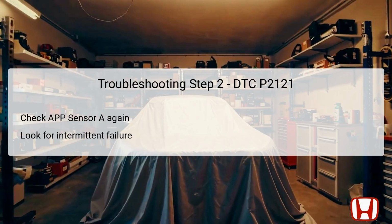If the readings are not fluctuating and the system seems to function correctly, the issue may be intermittent. It's advisable to inspect for poor connections or loose terminals, both at the APP sensor and the PCM. If you have access to an onboard snapshot of this DTC, replicate the conditions to see if the failure occurs again. Step 3 involves determining the potential failure area, which includes the VCC3 line among other components.